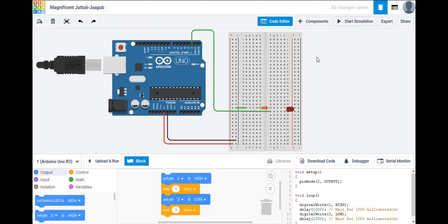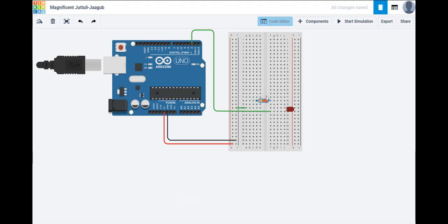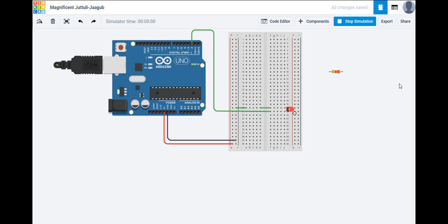I just want to show you why I've put this resistor in. For those of you who have used LEDs before, you will realize that without this in place, too much current will flow through this LED, and if you'd really connected this circuit without the resistor in place, it will burn out the LED. So let's just simulate that. Connecting across the bridge, and in place of the resistor we've got a short circuit there, and start that simulation up again.